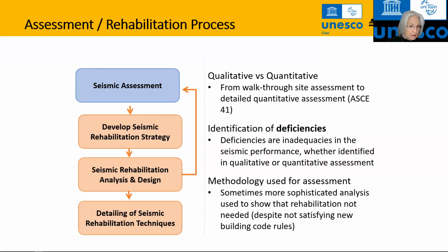When we are looking for an assessment, we need to develop a rehabilitation strategy. So why do we want to rehabilitate? To which level do we want to strengthen, for instance? What do we expect that the strengthening will do in terms of reducing the vulnerability? We need to then carry out a seismic analysis and design.